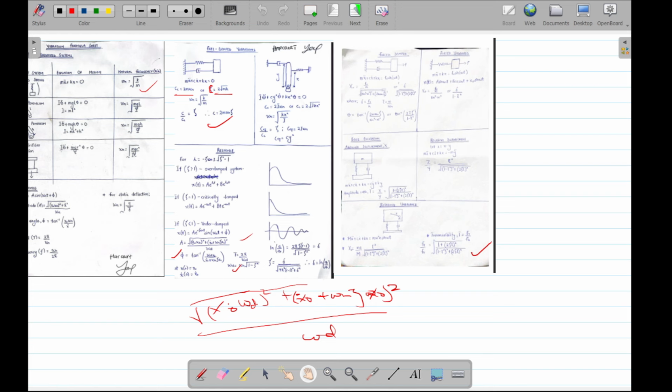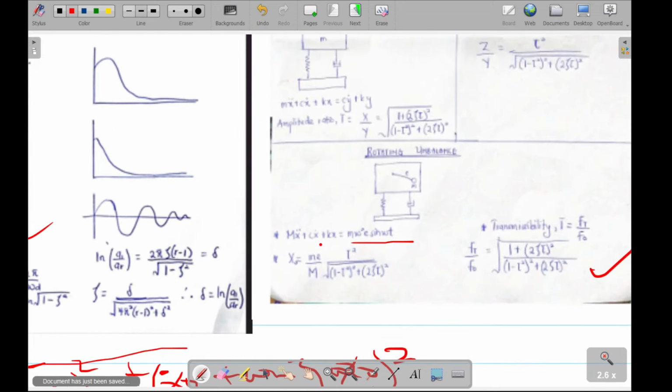It is the component here. Let me open it up. So this is the free vibration and the vibration force, and within this vibration force you have M omega squared e sine omega t. So this is the vibration force. The amplitude is just the coefficient of the sine function, which is M omega squared e. Good.